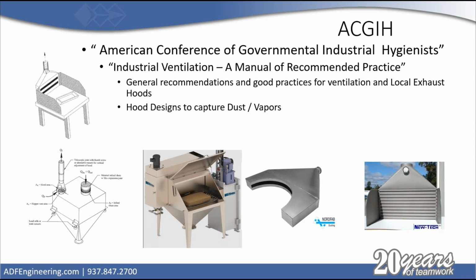The left picture on the bottom is just a representation of a tank that you might be gravity filling. And you take off your aspiration from there to minimize any dust accumulation in that head space, which we'll talk about a little bit later, why you don't want to have dust in those head spaces. The ones over to your right are just other looks at slot hoods. For instance, the third to the right is for aspirating drums, if you're using those, and then another look at a slot hood that's commercially available.